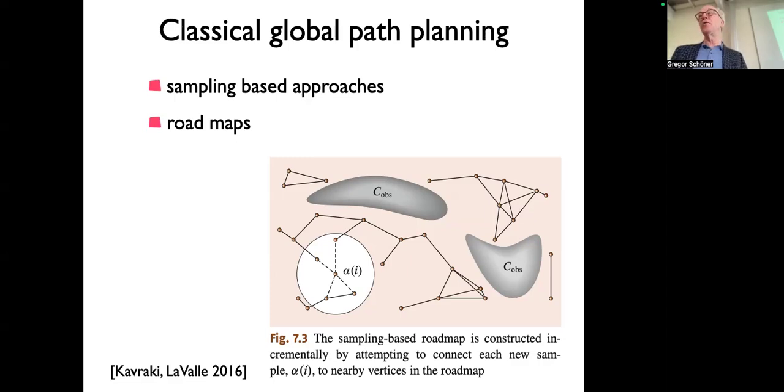So essentially, you're generating a graph of configurations such that you find out that you can move from one node on the graph to another without collision. And you essentially try different places like that, and then establish that you can move between those. And so iteratively, if you can, then you remove that point from the graph and so on. So over time, you develop a reduced representation, so that you only have to move within that graph, roughly speaking.